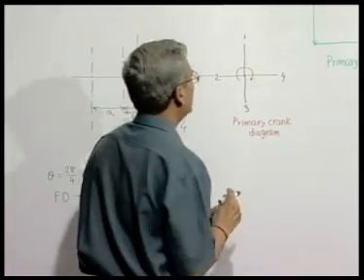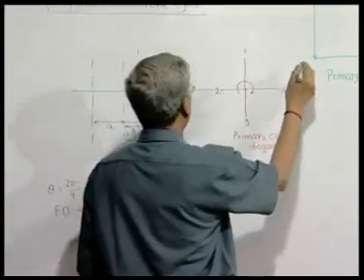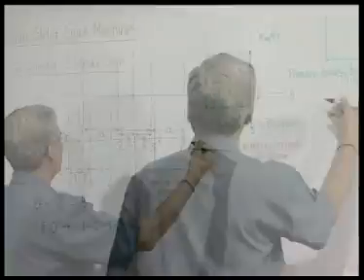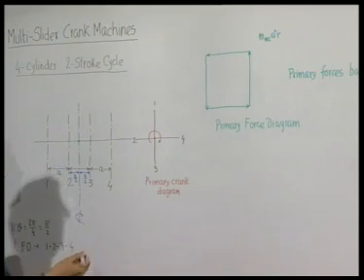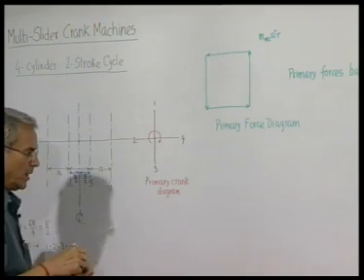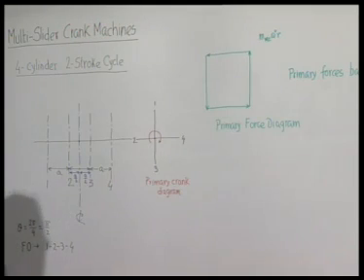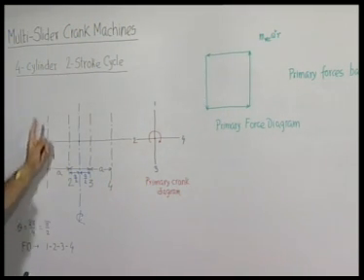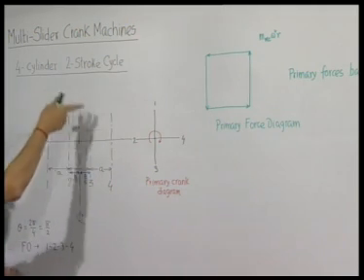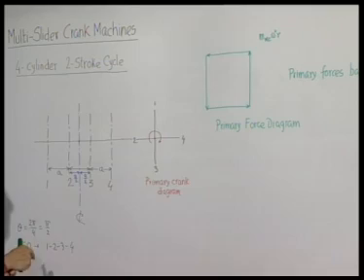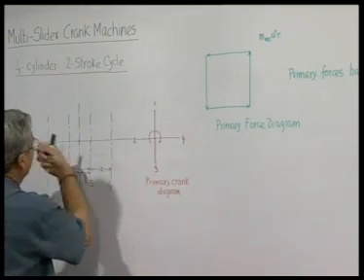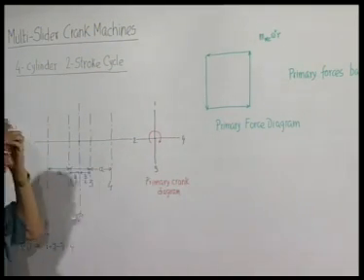Now, again remember that what we have drawn, we have drawn it viewing in this direction. So, moment diagram also we can do, and we have seen previously that there are 2 ways of handling. Suppose if there is a force like this, it will produce a moment which will be going inside the board, and when seen from this side it will be towards right.